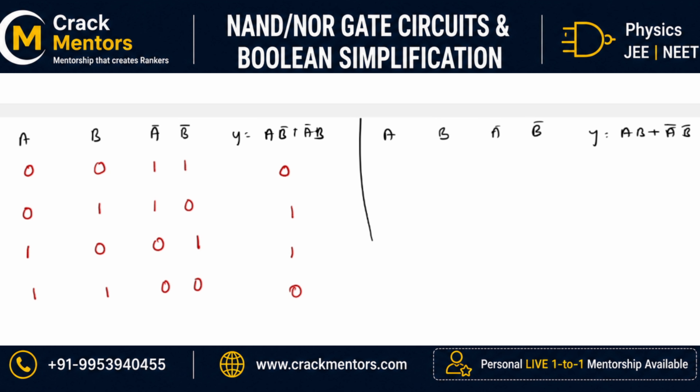Let us do the same for the XNOR gate. This is 0, this is 0. A naught is 1 and 1. So I will be writing 0 into 0 plus 1 into 1, giving me a value of 1. If this is 0, this is 1, this is 1, this is 0. What is the value? This is equal to 1 into 0 plus 1 into 0. The value again is 0 plus 0, this is equal to 0.